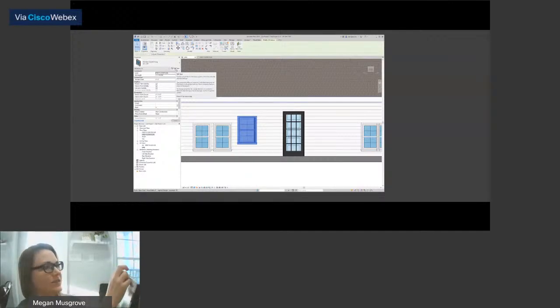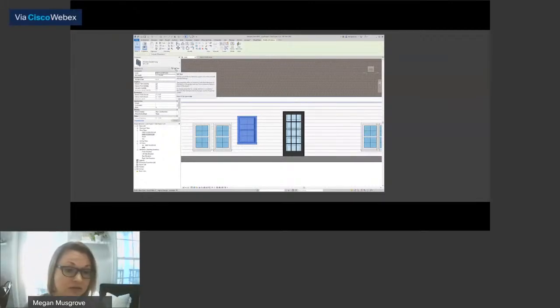reference for sizes. So if you're just playing around, you're never going to build your house, put in whatever windows you want, that's fine. If you are actually designing a house that you plan on being built, reference what sizes you can actually get. It's always going to be cheaper if you stick with standard sizes. And the big thing to remember is, even if you're not using standard sizes, there's going to be a limit. You can only go so big or so small, both height and width.